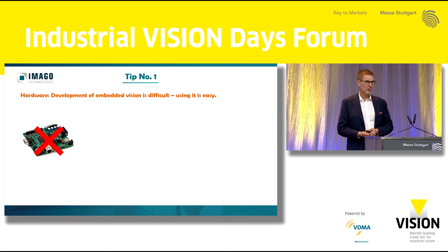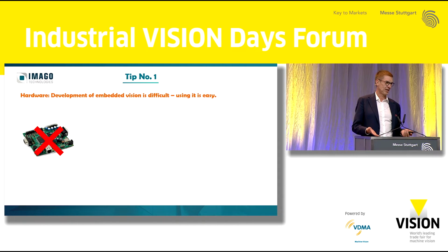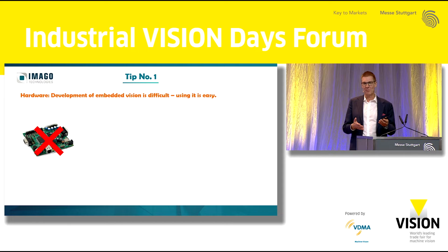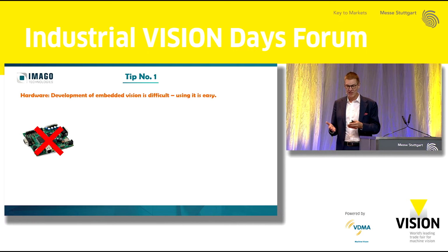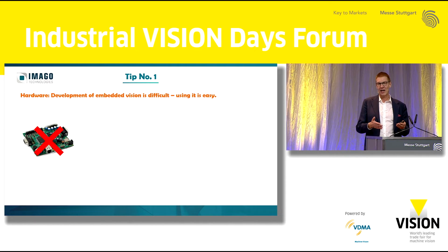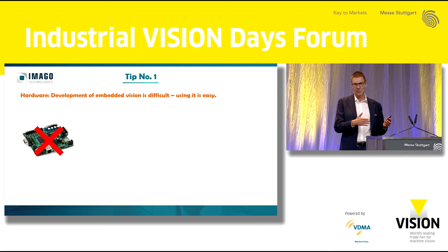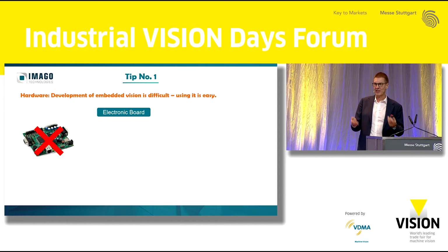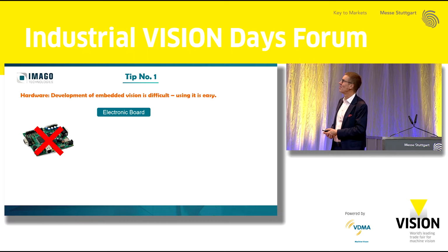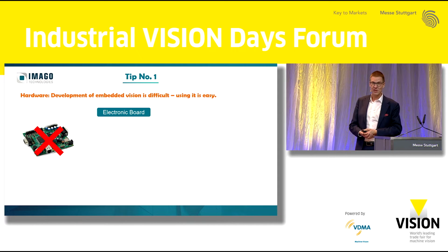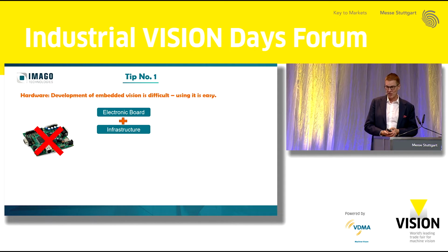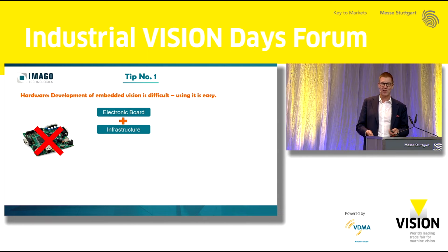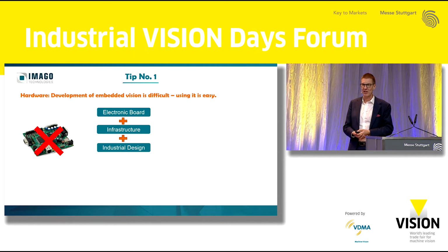So the tip is, how do you start? Are you starting with an evaluation board from a CPU vendor? And what are the steps between an evaluation board and an industrial product? There are many steps between these two situations. You need a specific electronic board, the infrastructure of the electronic board, the firmware support of the OS.